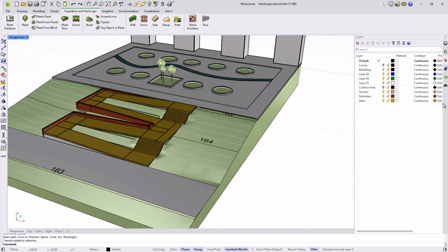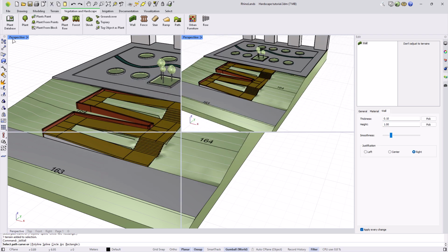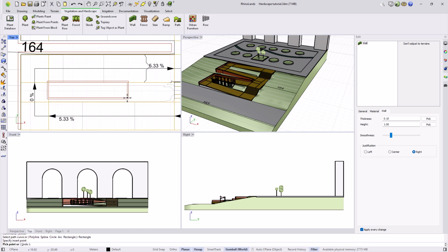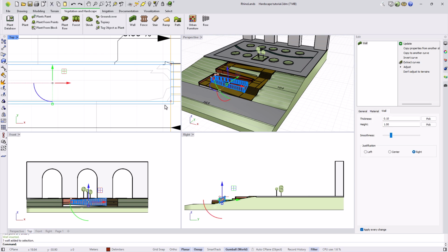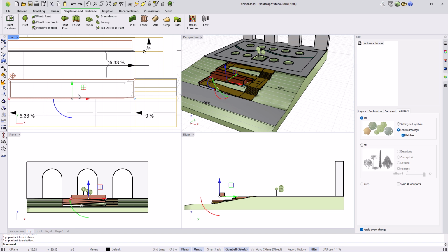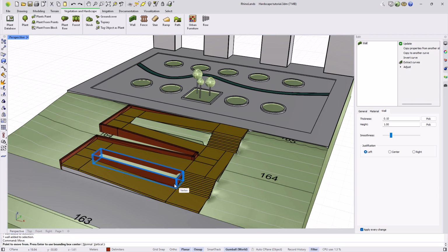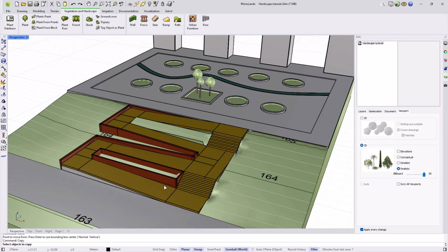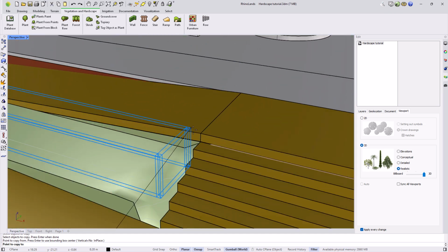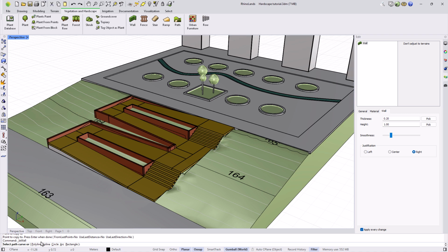Before moving on to the next commands, I will add some additional walls. With a value of 0.10 and a rectangular shape, to contain the interior terrain areas. I position it, copy it for the other rectangles. I also create another wider wall for the other side, which will follow the profile of the stairs using a polyline.